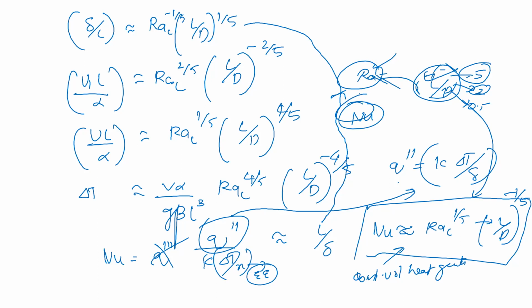The heat transfer to the wall is Q double prime, which is equal to Q triple prime into D. So the total heat transfer rate can also be determined, that is Q double prime into D into L. That value you can also determine through this approach. So this was just an understanding.